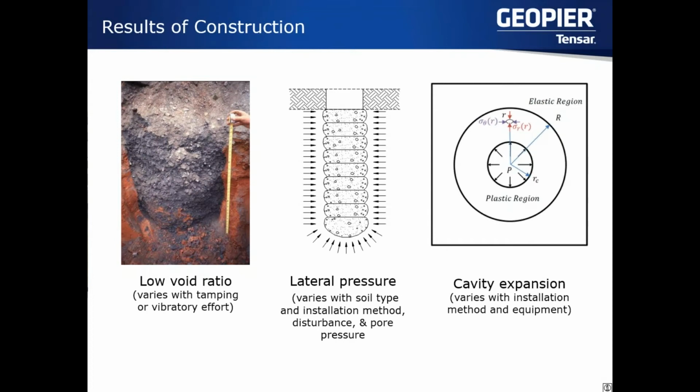Now, in some instances, depending on the loads, for example a lighter loaded building in organics that have very high water contents, if the loads aren't too high, we might be able to use a drill and fill system, and then use something like cement treated aggregate. We can use cement treated aggregate if the elements don't need to go too deep, and that cement treated aggregate, or CTA, will be built in the same fashion as our drill and fill pier up to the surface, but has a much higher stiffness.